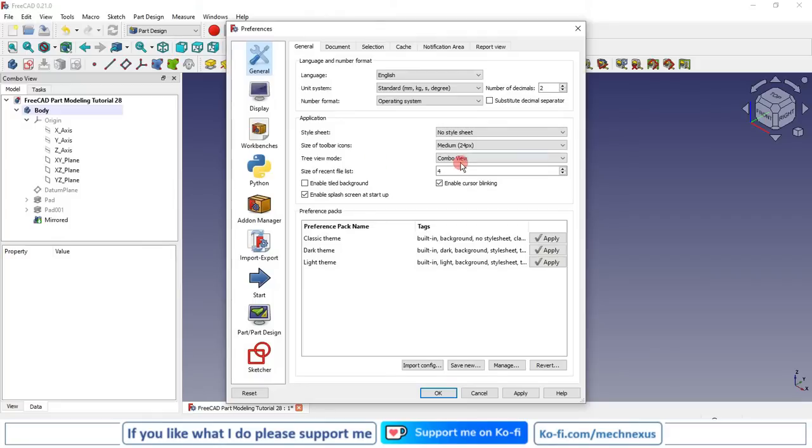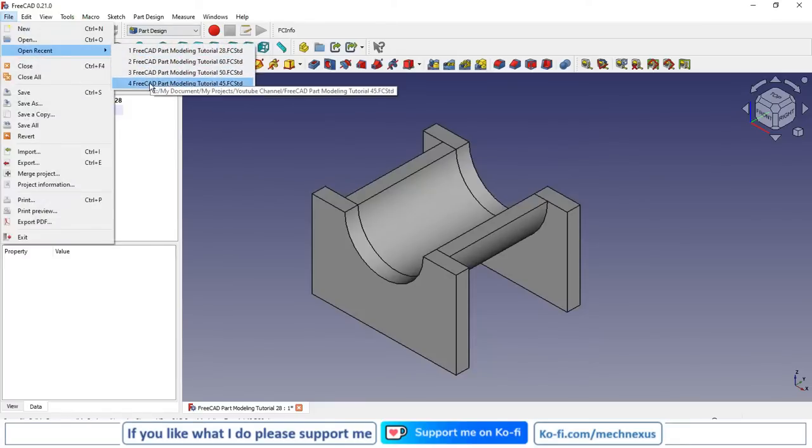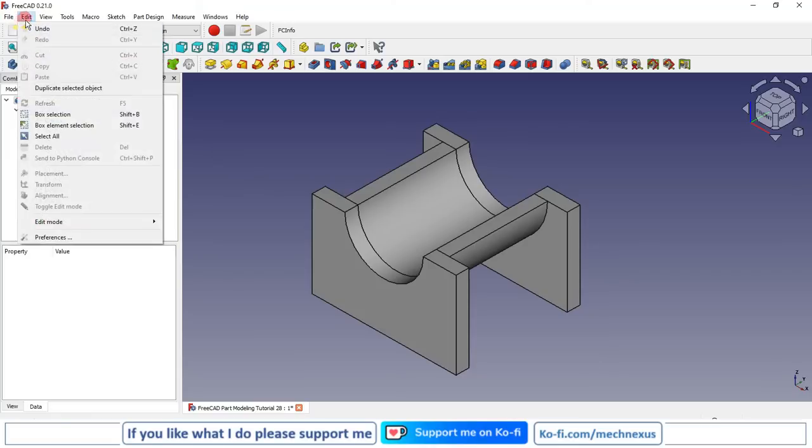Tree view mode is combo view. This is the combo view. We will see it when we do any part modeling. Size of the recent file list is 4. If you go here in FreeCAD, you will see the recent files. So here my default setting is 4 recent files. You can increase it up to 10 so that whenever you hover your mouse on the recent files, you will get a list of 10 recent files.